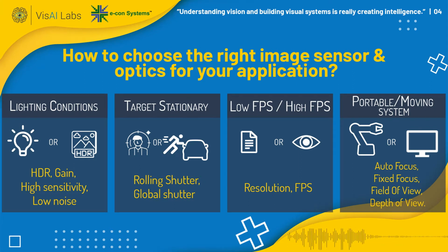The other thing we need to consider for an outdoor application is, are we going to use these cameras for night vision as well? When I say night vision, whether it is just low light or we are not going to have any light at all. If it is a low light application, then we will have to choose a bigger sensor size that will provide better image quality at low light. If it is a smaller sensor size, then we are going to get a lot of noise in low light. In the other case, if there is no light at all, then the sensor has to support the infrared region as well. So look for quantum efficiency in the infrared region.